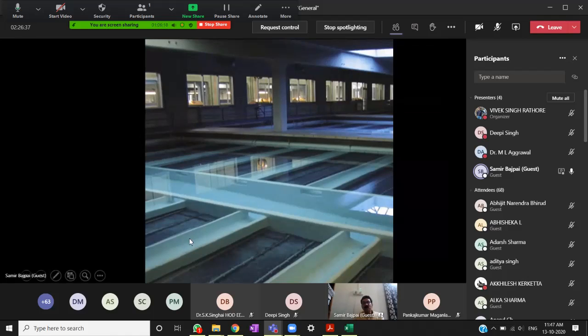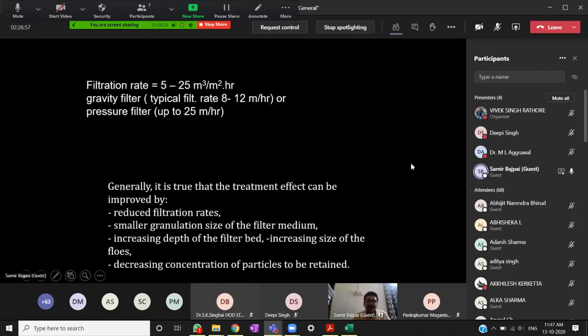And these are wastewater troughs. These are nozzles to spray water coming from coagulation, flocculation. And this is a sand bed. And these nozzles spray the water on the sand bed. Water percolates down. Treated water is taken from the bottom through the under drainage system and taken for disinfection. These are some, you can say, operating data.